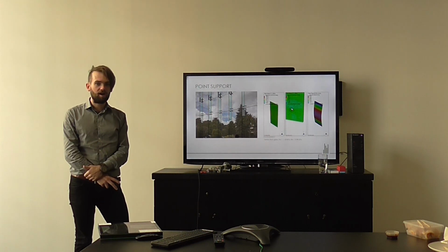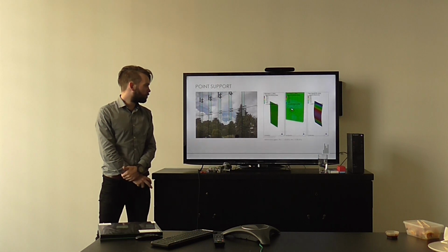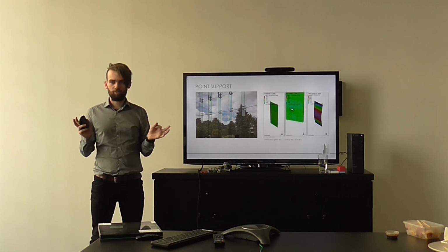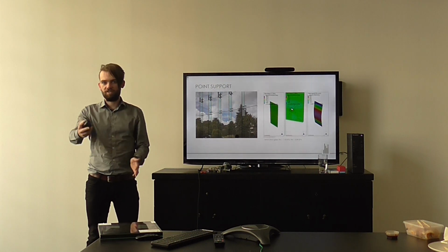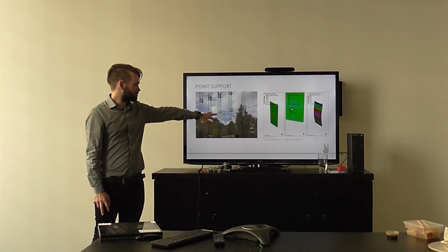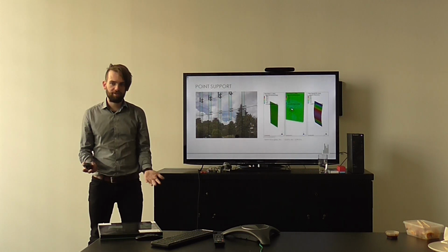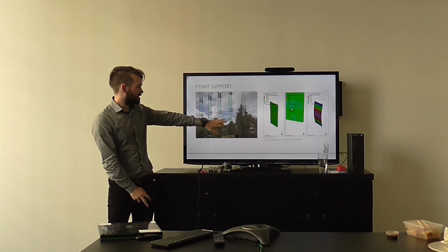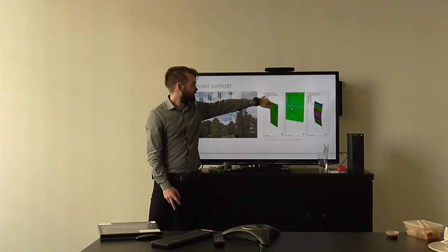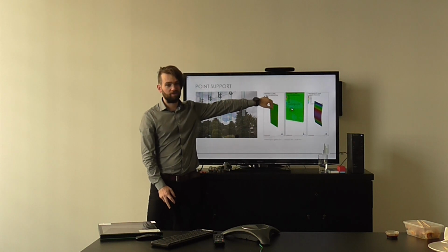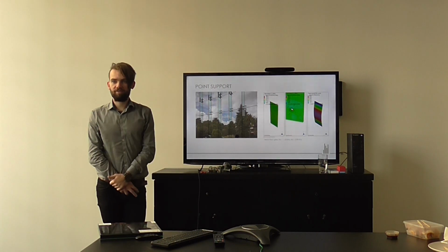The other one that often comes up is what we call point support glass, or patch fitting glass, or planar glass. There are some other terms that people use, and essentially they're walls where the glass is fabricated with small holes at locations designed by consultants and engineers, which are then fixed with these rotule fixings that you see here, back to posts, glass pins, whatever you like. So as you can see here, this is indicating the stress, and if we compare this to before, we're up around 104 MPa here, so that would not work for this thickness of glass.